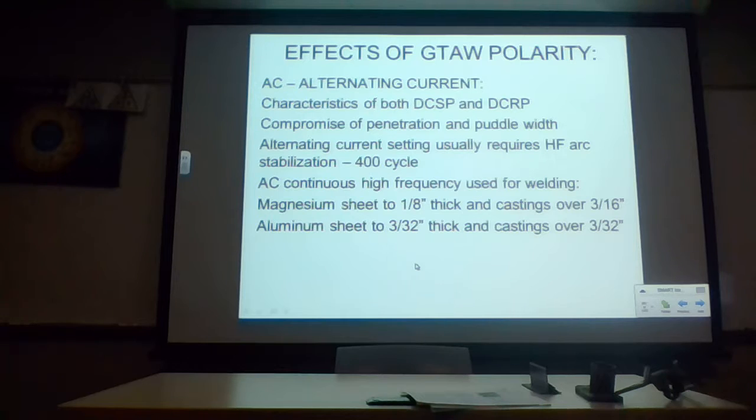Aluminum and magnesium generally oxidize really quickly. If you just clean aluminum, within about 20 minutes of cleaning, in most cases, there's already an oxide film that's building up that will kind of impair fusion. The same thing is true with magnesium. They're just natural metals that oxidize without too much additional anything happening to them.